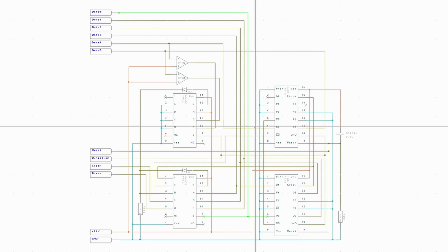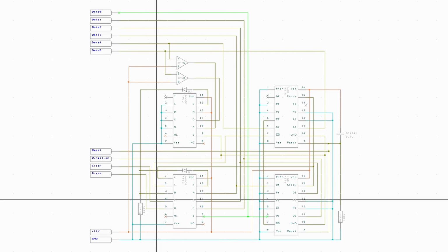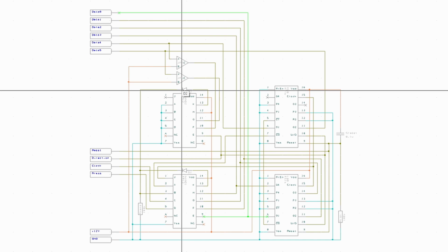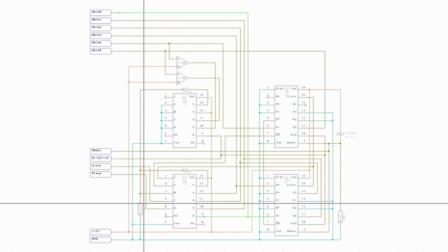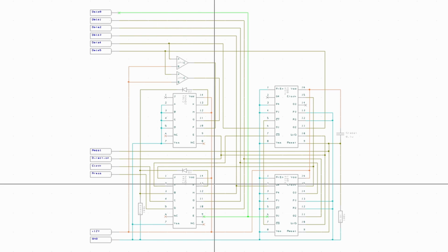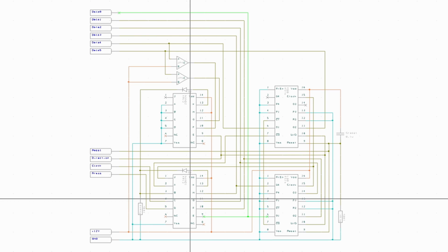Let's add a bit more. I think the next thing I want to put in is these components over here. So both of these NAND chips have a diode going this way connected to a resistor. The function of these two diodes connected to that resistor is so that we can take both of these outputs of the NAND gates and combine that together. Essentially, we're taking two 4-input NAND gates and combining it so that now it's a single 8-input NAND gate. And if you go back to the original design circuit, you'll see why we needed that.